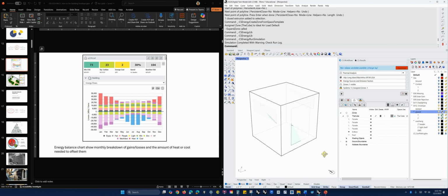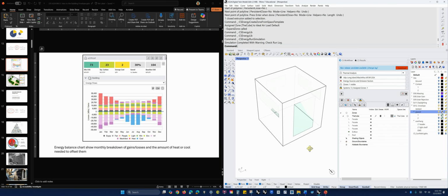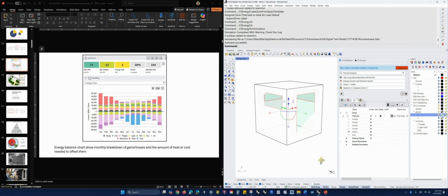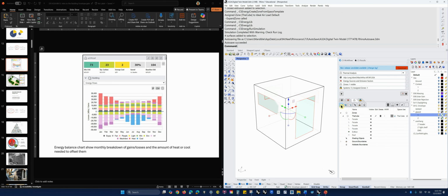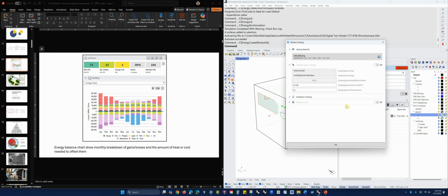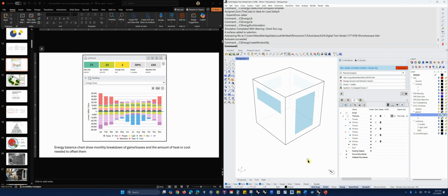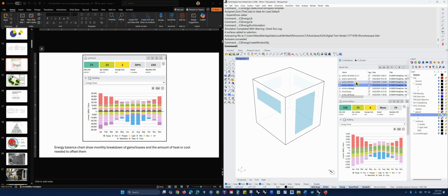Okay, so I have this glazing setup that I want now to be my actual glazing from my thermal zone. So if I select those objects, so all my glazing is selected, and the icon next to the add zone is add window, and I'm going to keep my default glazing like I had for the automated glazing that I put in before. Now I have actual glazing that I can run a simulation on. I did that. Then I tried overhangs.